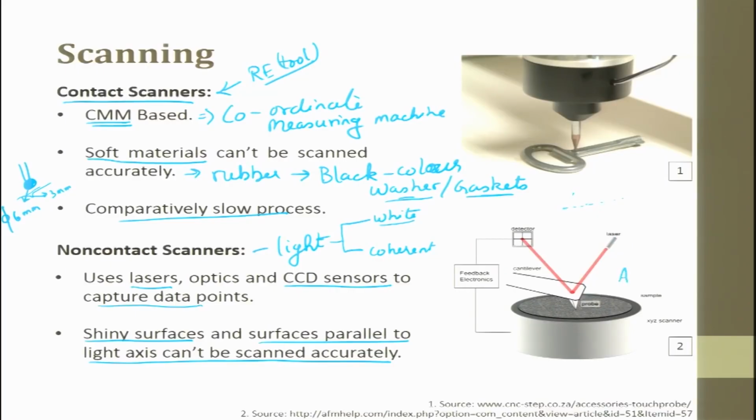This is nothing but an atomic force microscope, wherein if you want to get data in the nanometer or angstrom range, you can use this atomic force microscope. Here a laser hits the backside of the probe, where a reflecting surface has been put. The laser hits and reflects, and it falls on a diode.